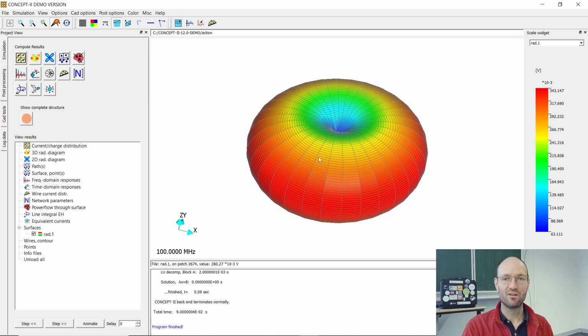And this is what saved us, let's say, many years and many decades in EMC, that we had fairly large equipment under test where we would measure the emission, but the frequencies were so small that everything radiated more or less like a dipole. And as I said, it's very simple to find the maximum emission of this dipole.